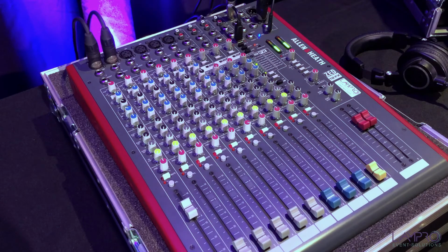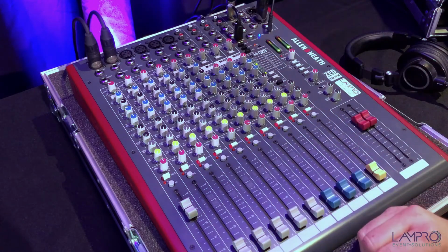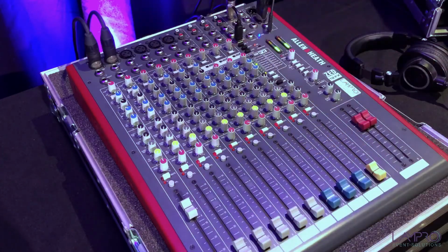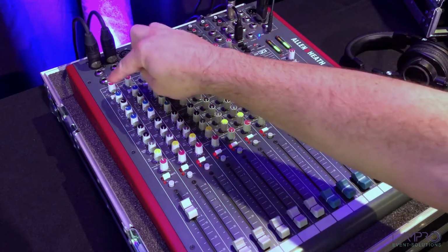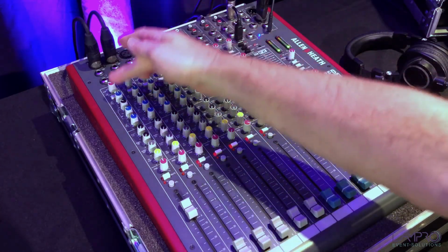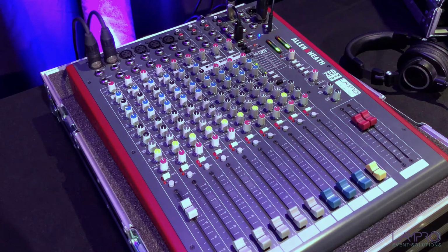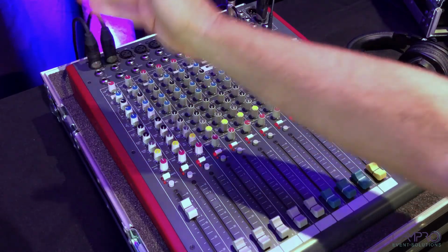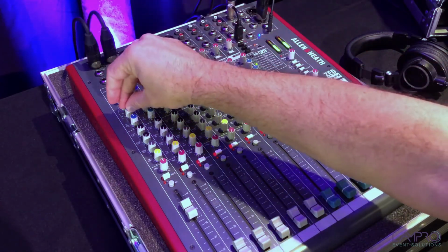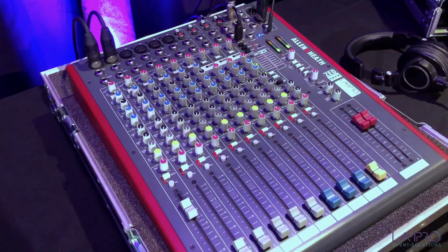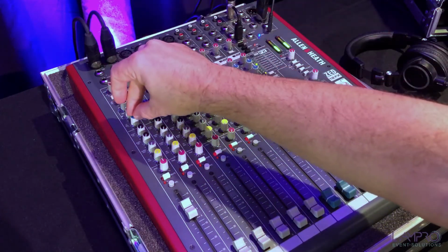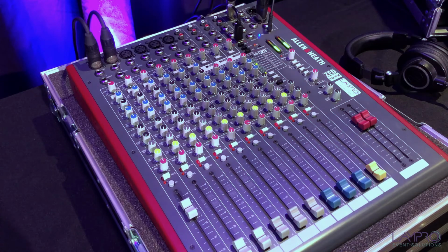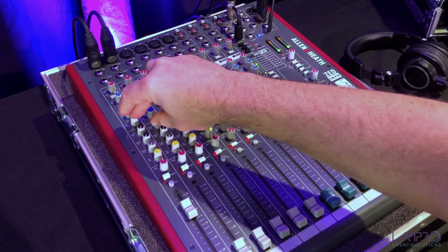Right, so let's have a look at the EQ setup on channel 1. Since I can't do a lot of adjustments on channel 2 with a 1 kHz test tone, we'll use my microphone as an example. You'll see the HF shelved EQ at the top is in the center position, which means that no adjustments are taking place. The mid-sweepable EQ section has a certain frequency selected at 500 Hz, and it's being cut with -4 to -5 dBs to get rid of the mids there at the moment. And the LF shelved EQ at the bottom is also in the center, which means that no adjustments are taking place on frequencies that are 80 Hz or below.